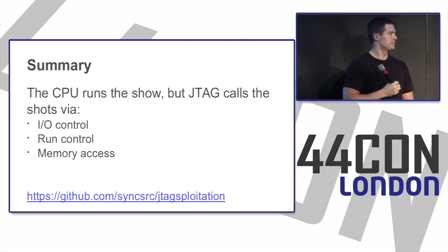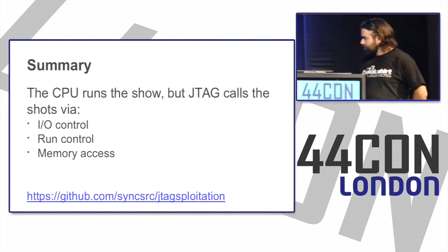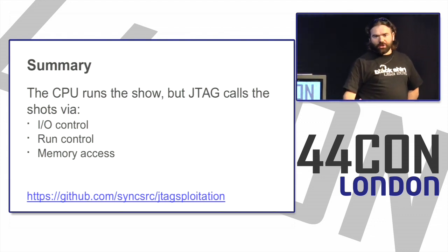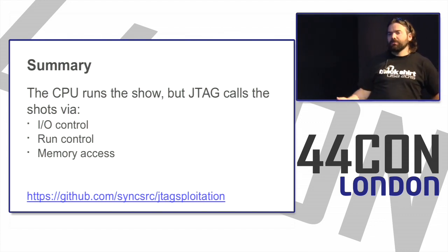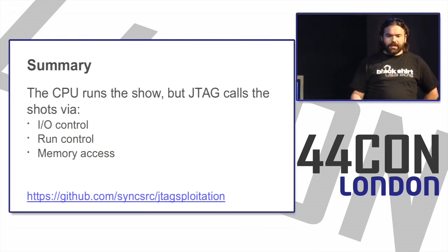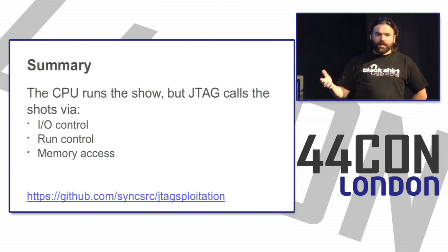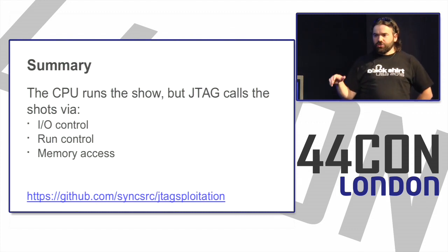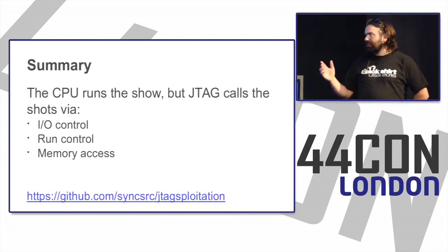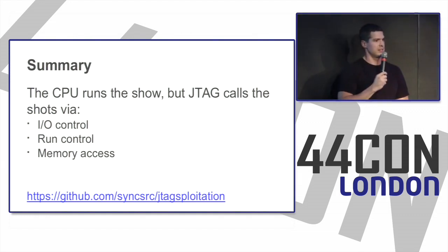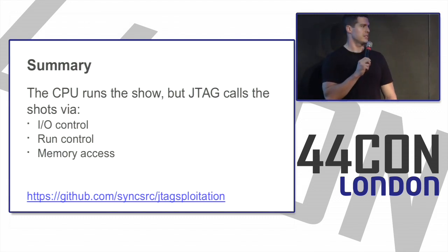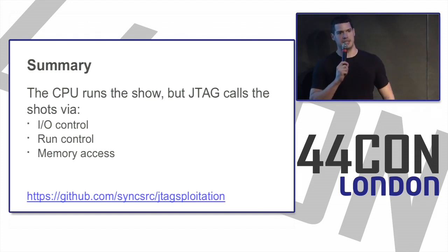Yeah. So to add on to that, though, there are some chips out there that do lock out certain functionality of JTAG, whether they disable JTAG on production parts. That is feasible on lots of devices, but very rarely actually happens. Some devices have tiered JTAG access, so you can lock them out of accessing certain memory regions. But again, that requires the software and the hardware manufacturer to both properly configure those features, which doesn't happen all the time. A lot of times that doesn't happen because the company making the chip that puts all those options into it is not the one selling, say, the router, and if the company building the router doesn't know or care, it doesn't get used.